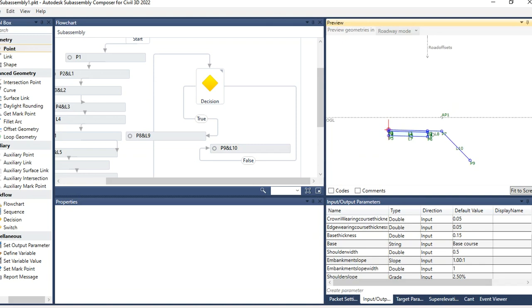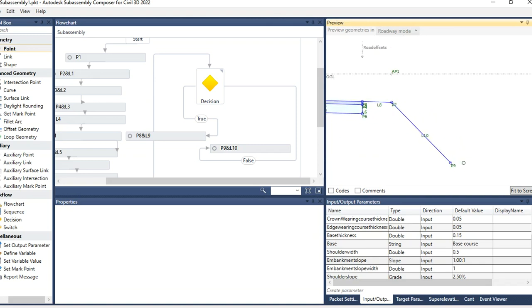So now this is what we have designed from the design, or what we have been given by the engineer. So sometimes if we don't want the embankment slope width of 1, we can change it, or the slope we can also change. But remember that if you change this slope, it will also change whenever we are in fill.